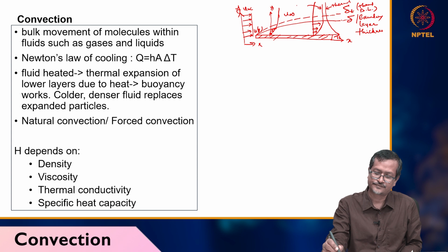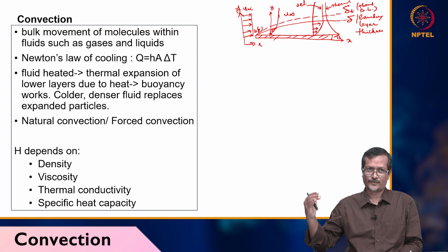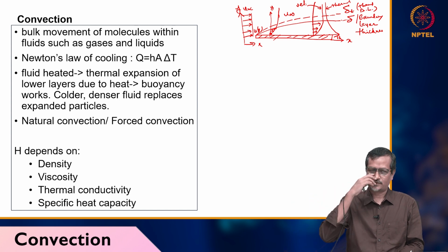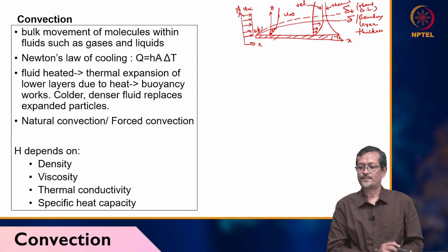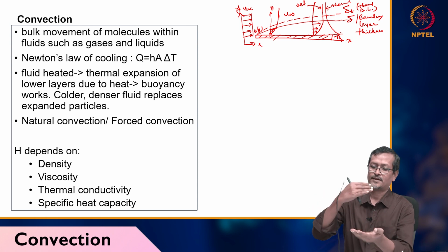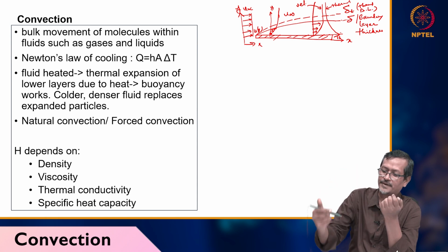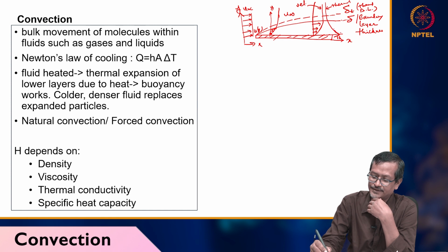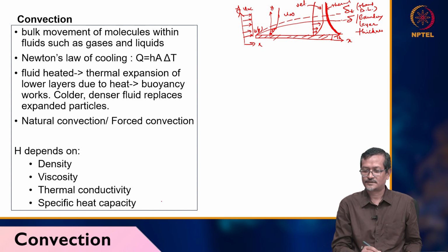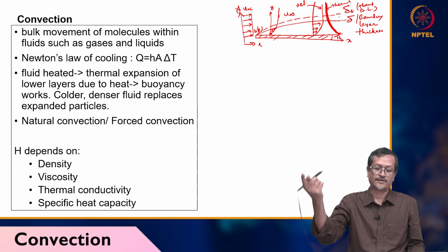This is for velocity, and this is for thermal. So you can see the thermal boundary layer near the wall, it is on the right side. What is happening? Particles are not moving near the wall, so temperature is higher. So if you go away from the wall, like say the wall is here and you are moving up, temperature is lower. But if you draw that one properly, it will come like this. You see this thick line I have drawn, this is the thermal boundary layer it is creating. This gradient is created within this boundary layer, and the upper portion is going to u infinity or T infinity.